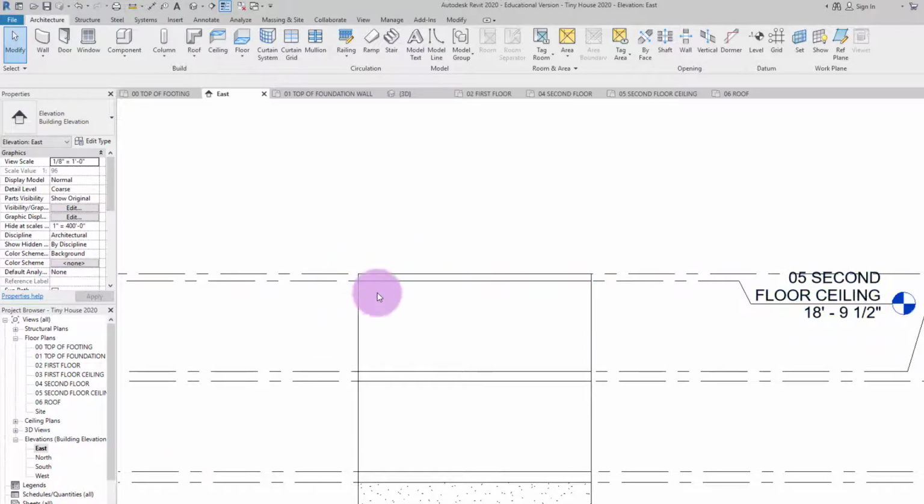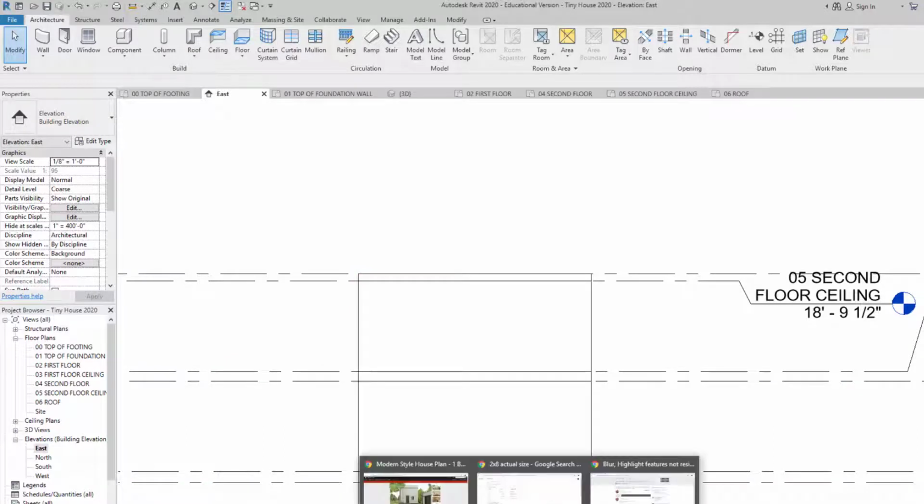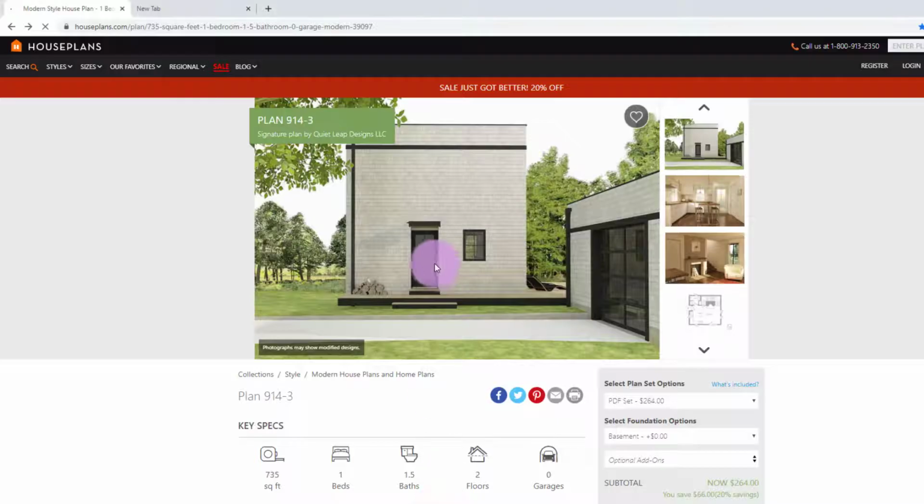Now this building looks flat, but I'm very skeptical of how they are actually doing that. I think the roof line's actually right here, and they're going to do a hip roof behind that, and then you put these little tiny walls up, and it gives us this illusion that this is a flat roof. It gives you that nice aesthetic.